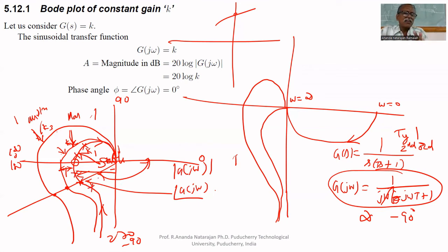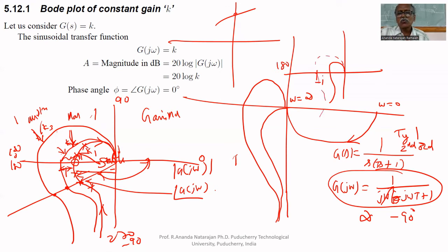You can notice that if k is increased, the plot is magnified. Therefore, in other words, how much gain is required to bring the system to the verge of instability? That is called gain margin. Suppose the original plot is like this. It crosses 180 before -1. Suppose you increase k so that it goes through this -1. How much is k increased?